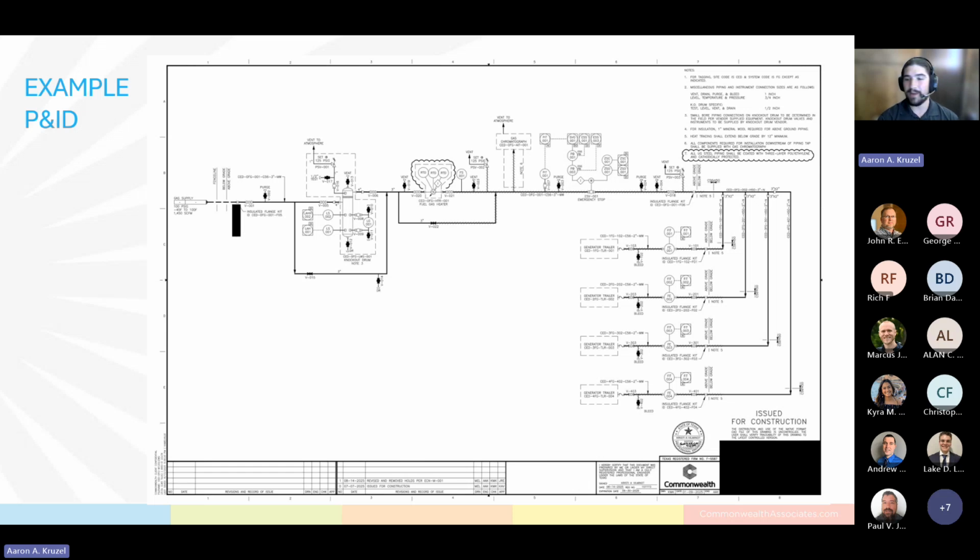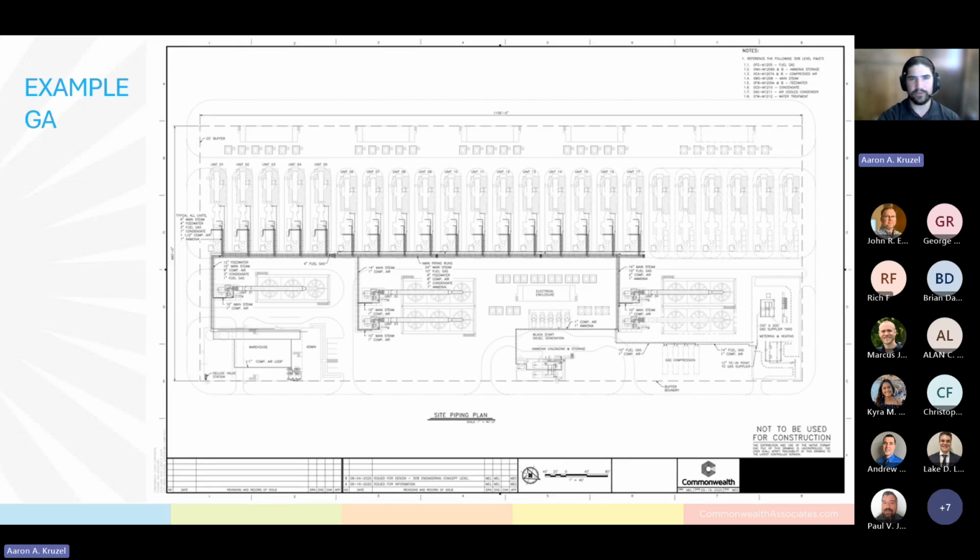Based on what we've modeled, we can size the equipment and size the piping correctly, and then input it into our P&IDs, which in turn can go to our general arrangements. It's generally how we make the model: pulling pipe lengths and estimations from the GAs themselves, and then coming back and adding the line sizes, equipment sizes, all that jazz. So this is more the end result after completing the model.